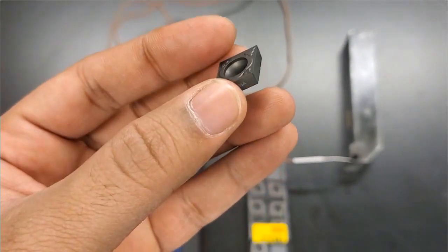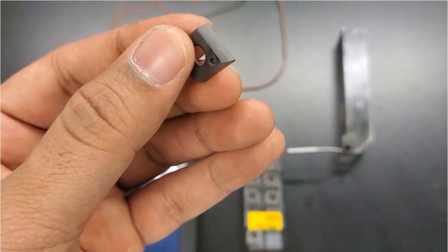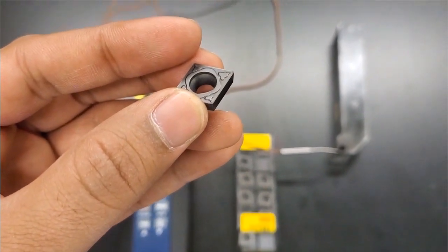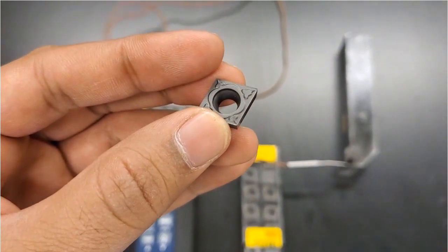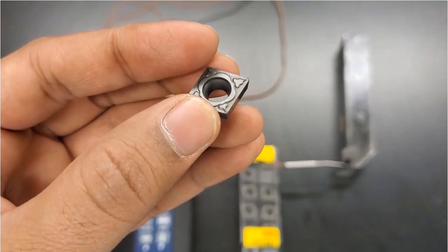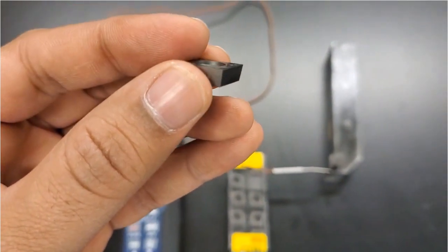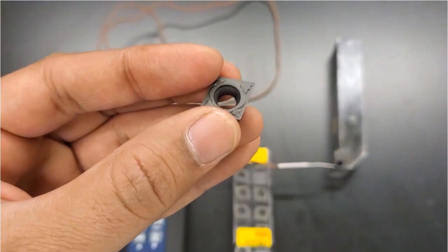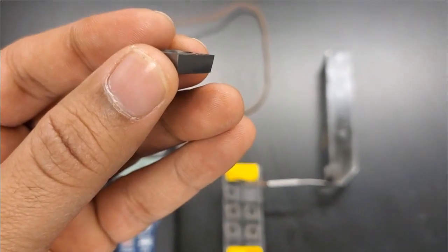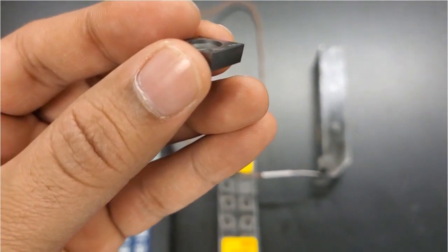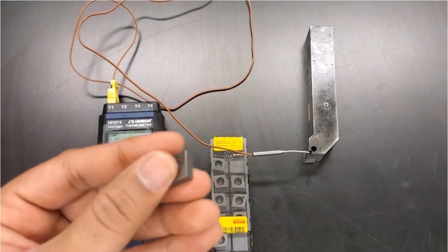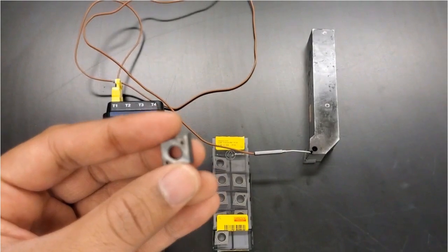Okay, so what you see here is the turning insert, and if I want to measure the temperature of this insert, I have some ways to do it. So I know I have the thermocouple, but how do I place the thermocouple at the location that I want? It's impossible to keep the thermocouple at the very tip of the insert. If I want to place it at the flank face, I would have to use something like a sticky tape that is thermally resistant, but because of the chips that are continuously formed, there's a good chance that it will be ripped off from its position.